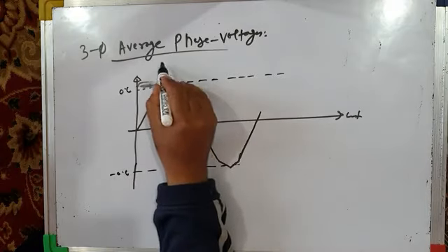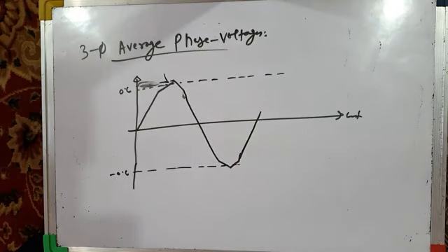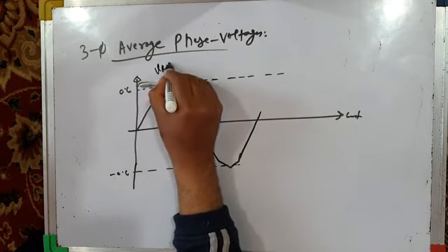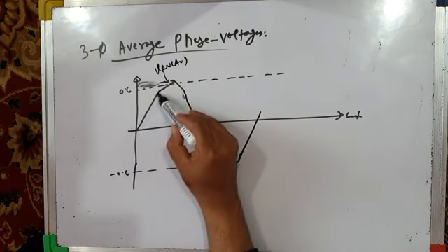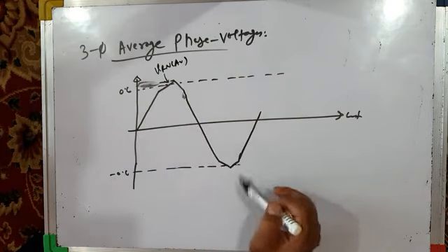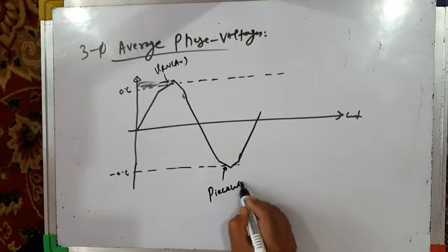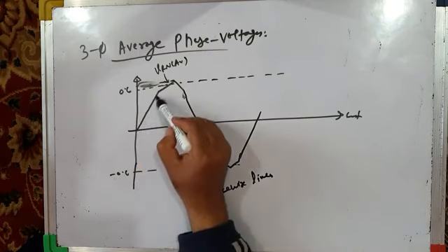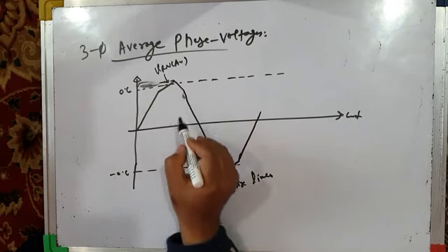Now you can see your phase voltages are not following the pole voltage pattern because modulation index is very large. Your phase voltage VRN average is piecewise linear. It's a linear line, then linear, then like this, piecewise linear. So I will write here piecewise linear. For example, the positive half comprises 1 line, 2 line, 3, 4. Similarly, negative half cycle.